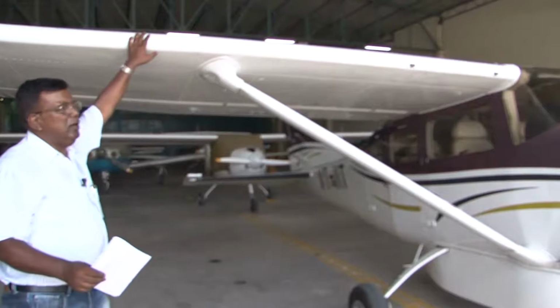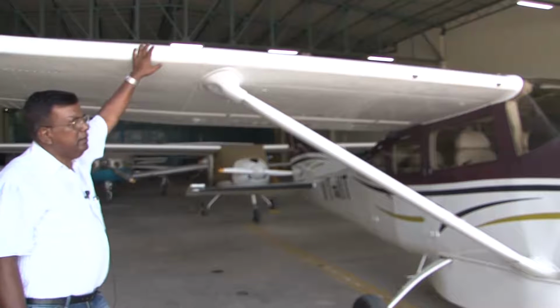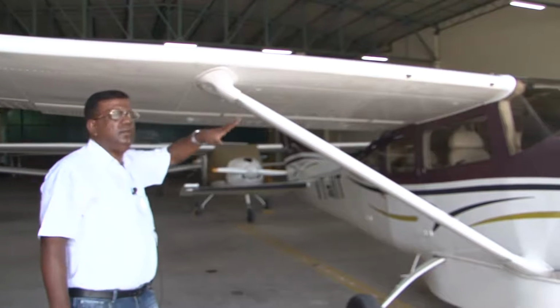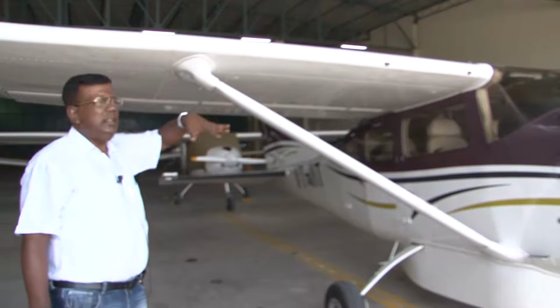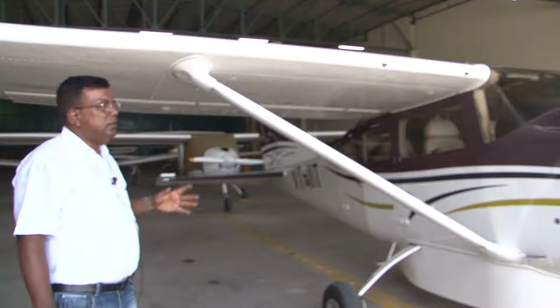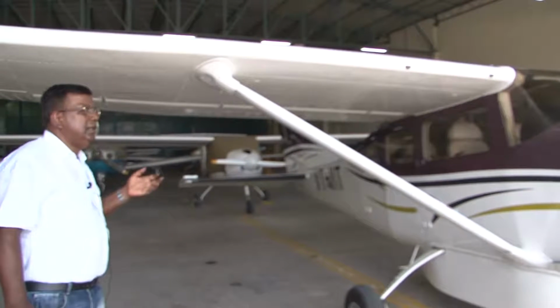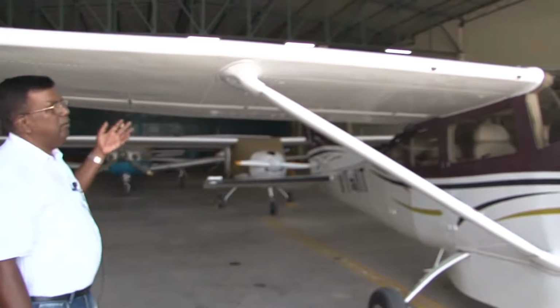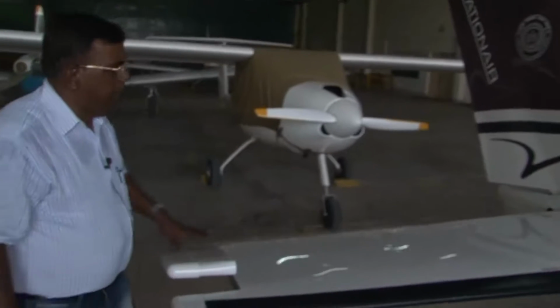So that will give you around 25, 27 meters per second. So the stall speed will be around 22, 23, and takeoff will be around 27, 28, depending upon the flap orientation. Right? So you could see that all these numbers are making sense based on whatever we have studied there.